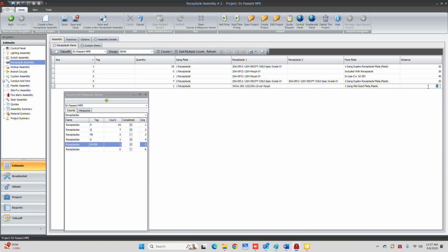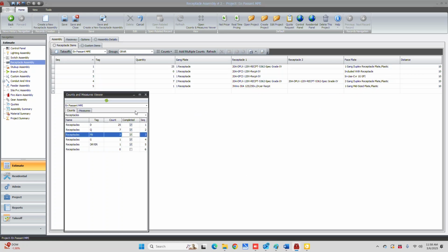and then I'm going to go 10 foot to get above the ceiling. And I'm going to change these others to 10 foot as well, since we actually scaled the drawing. You can use this as an average and only scale the home run, or you can just get above the ceiling. So now we need to enter 3 floor boxes.